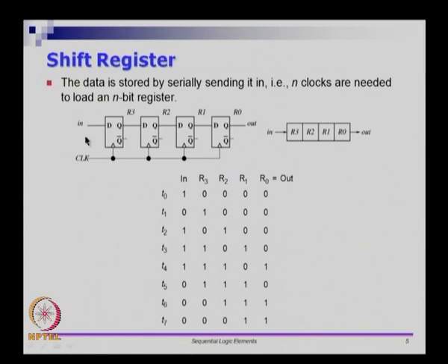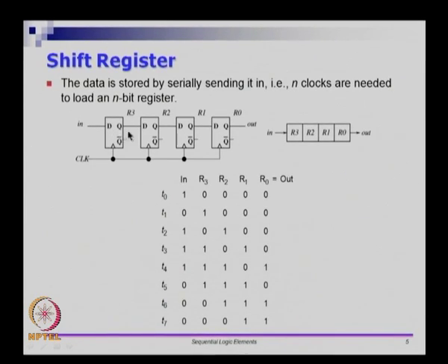So the key difference is, there is only one input bit, we do not have multiple bits, we have only one input bit. We take that input bit and give it to one flip flop, the Q of that is connected to D of another flip flop and so on. So you can think of it as people holding hands left and right. So from one side you get the input and from one side you give the output, it's like that.